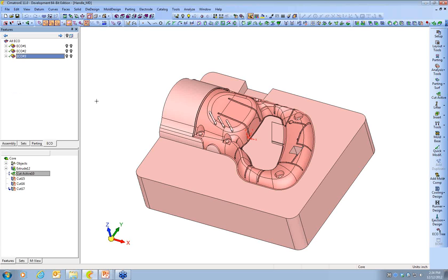And it really brings me to my last option, dealing with engineering changes. This is the option that we would use for whatever reason when we want to completely avoid feature updates. Completely. So essentially what I'm saying is we want to take the new data and glue it directly into the bottom of that pyramid, the bottom of your design at the component level. So to prepare for that, we've already marked the third ECO as done. I'm going to create a new folder for ECO4. And as we've done before, we need to add the latest part data in.